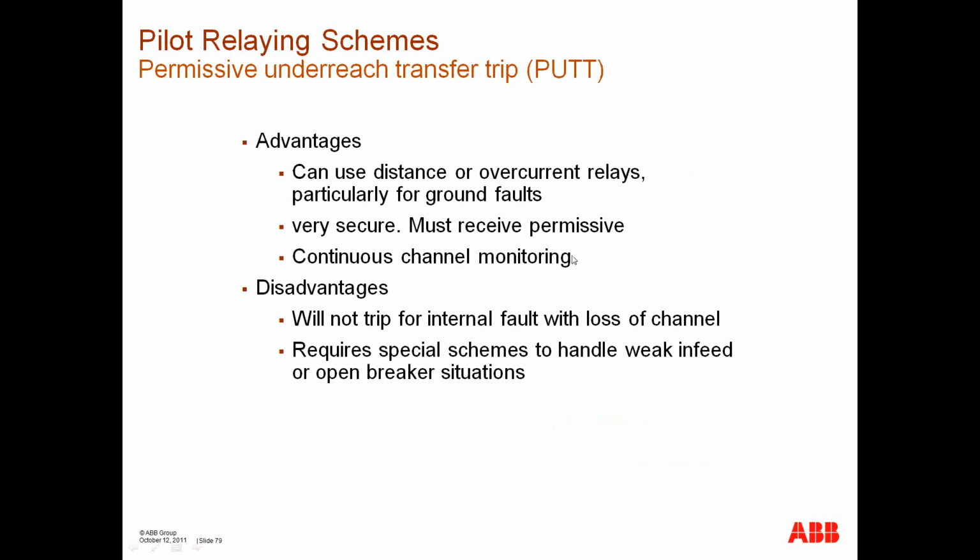Advantages: can use distance overcurrent, it's very secure. It's continuous channel monitoring. Disadvantages: will not trip for internal faults with loss of channel, and require special schemes to handle weak in-feed and open breaker. Well, that's pretty simple logic.